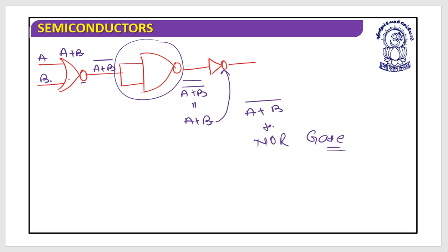This is one of the approaches. If you know Boolean algebra, this is the quickest approach. If you don't know this, what you are supposed to do is apply the different combinations of A, B, Y, and these combinations could be 0 0, 0 1, 1 0, 1 1, and find out the values according to the truth table. If it is 1 1 to the OR gate, then the output will be 1, then I will perform a NOT operation and so on. Then just try to identify which gate it is. I hope this is clear. Do you understand it? It is a comparatively longer approach.